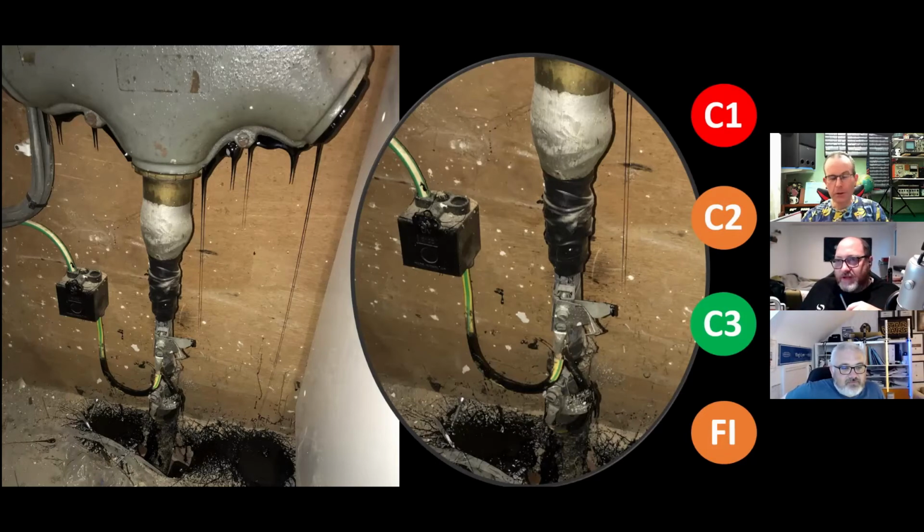Yeah, this one, we've got the pitch leaking out, which is that black substance, which when it's cold is completely solid. And it only flows out like that when it gets hot. So why would it get hot? Indeed, why would it get hot? So this is more about thinking about what's going on there. It's not just, oh, there's some mess fell out on the floor. It's what has caused that to become a liquid state and fall out onto the floor and make a mess.